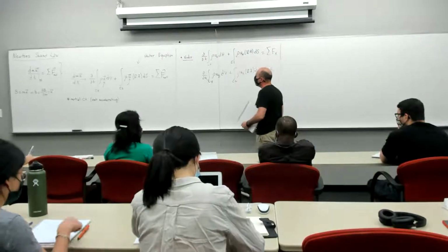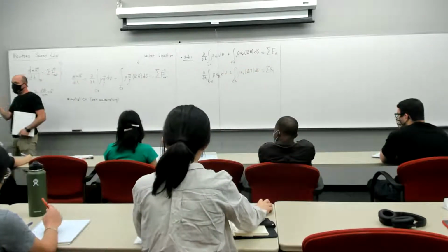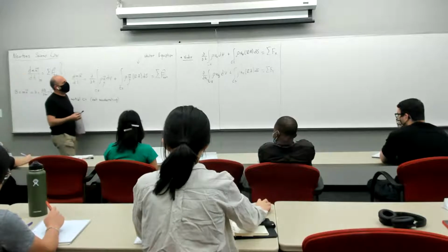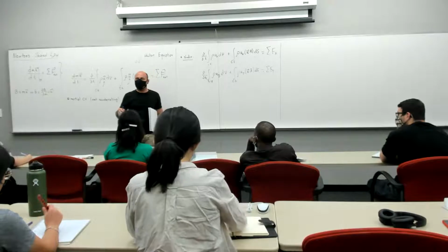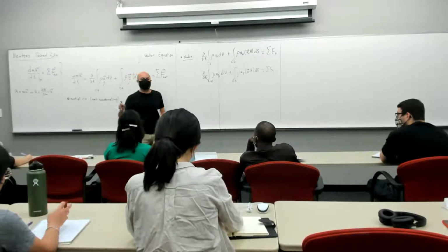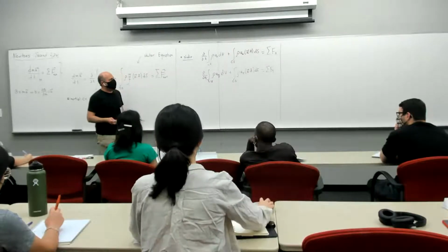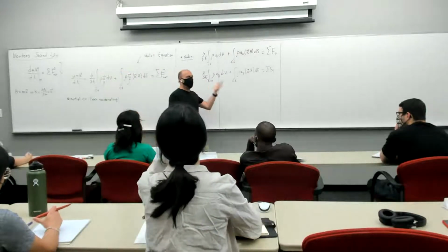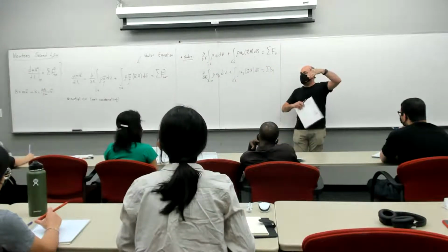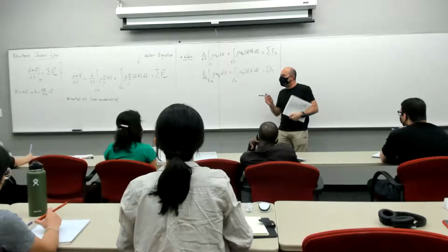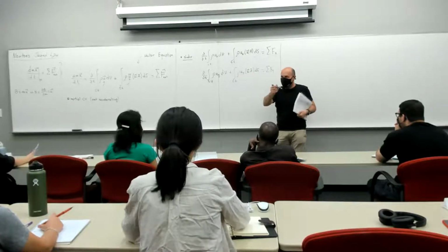Now, like I said, we're not going to use this form a lot like we did with mass conservation. We're just going to use it to try to deduce forces exerted on a control volume, like thrust, for example. Now, something really useful happens when you choose your control volume in a way such that the surfaces are aligned with the inlets and the outlets so that u dot n becomes either u out or u in, right?